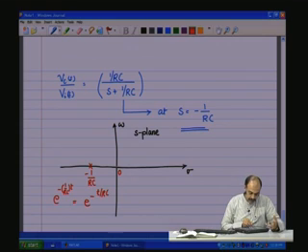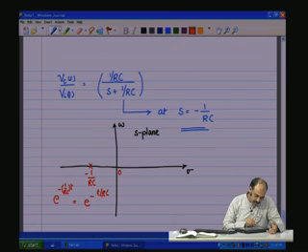So, that is the integrator. As this pole starts moving away from the omega axis, R C becomes smaller and smaller, which means the time constant is fast, which means that any excitation, after it is removed, will decay very quickly. So, that is basically the meaning of the pole location.